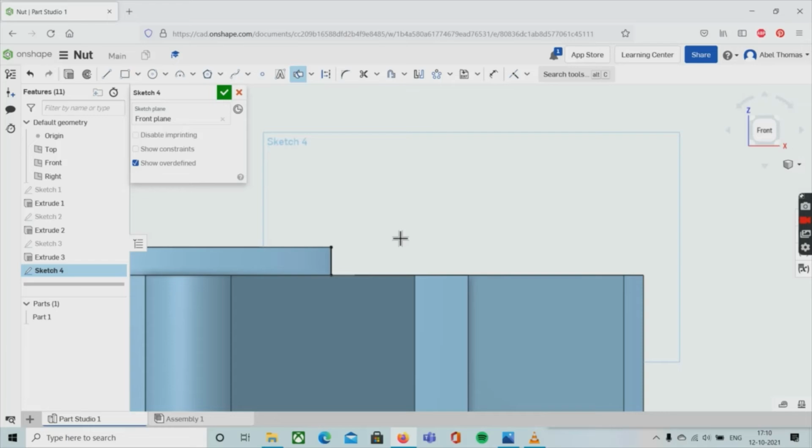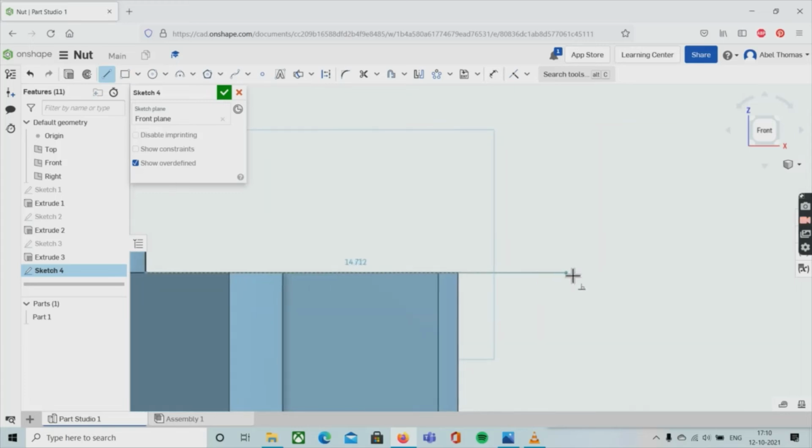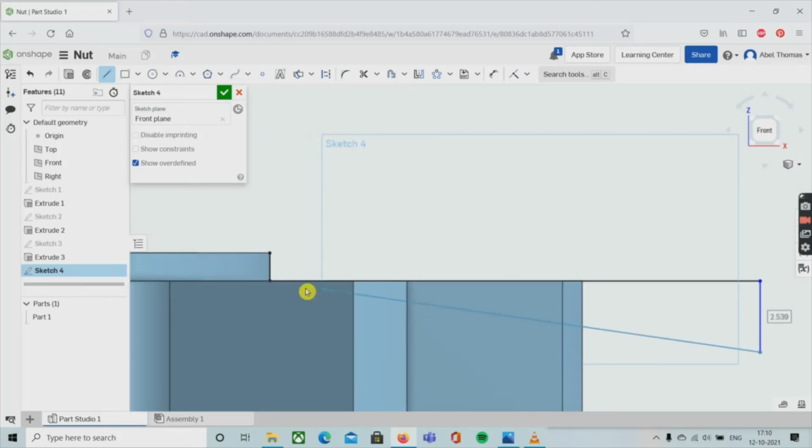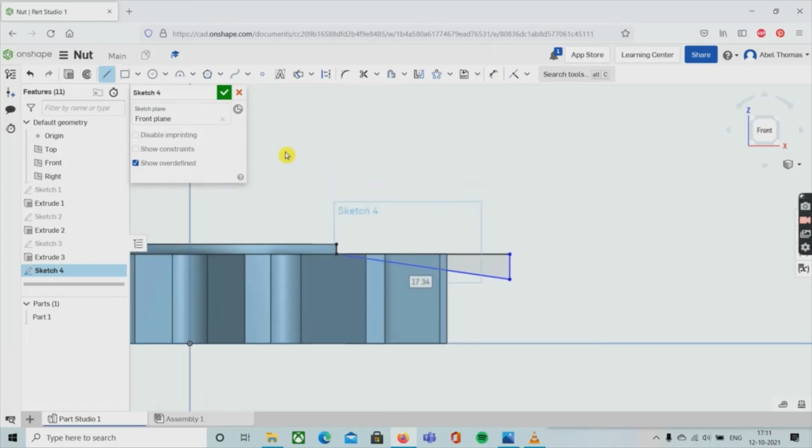So we will click the line tool again, start from the new point we just created, draw a horizontal line, draw a vertical line. You know, this constraint is shown by that dash just below the tool there. Okay, so we'll press here, we'll add dimensions later. Now we'll coincide that tool to this point again. So we have just drawn our triangle.